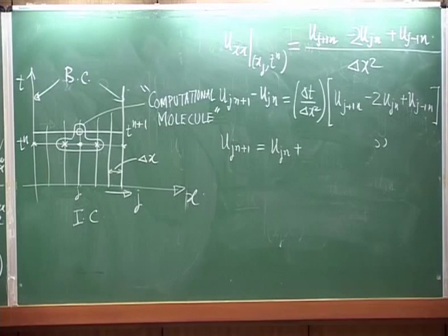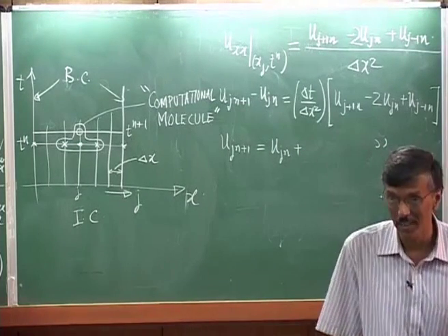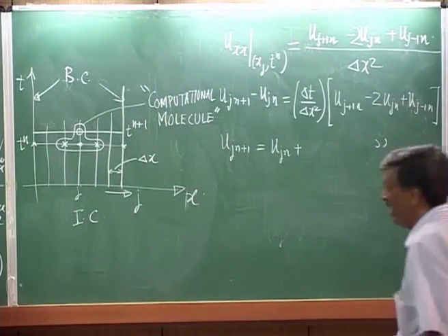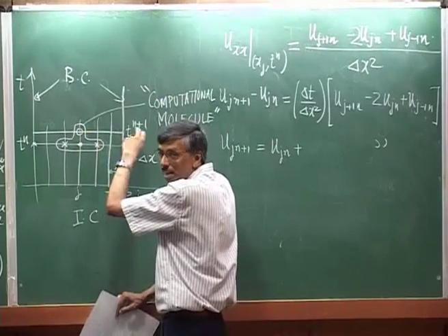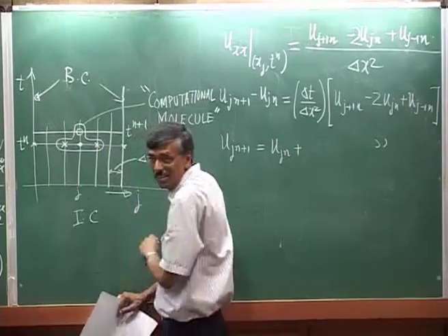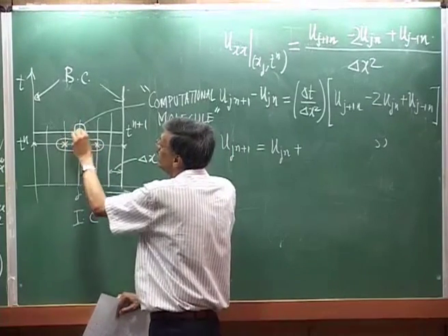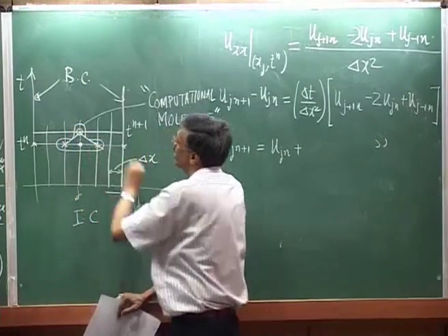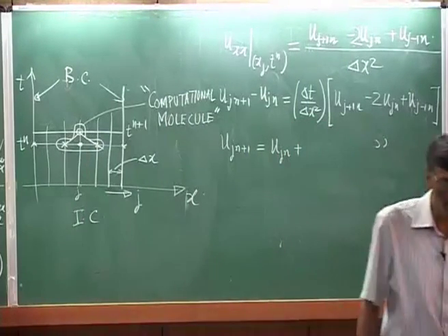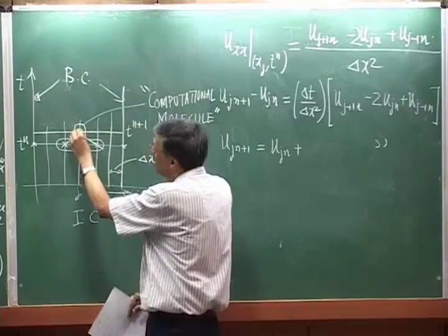We have just done this classification and we have figured out the information should have propagated along t equal to constant line. Are we getting that here? If I were trying to figure out the solution at this point, then my information should have come along t equal to constant line. But instead what we are getting is information from this. It is coming from a region which is given by the apex at that point and these 3 points.